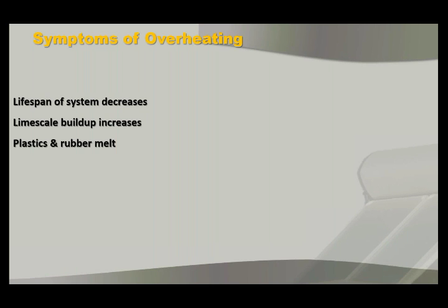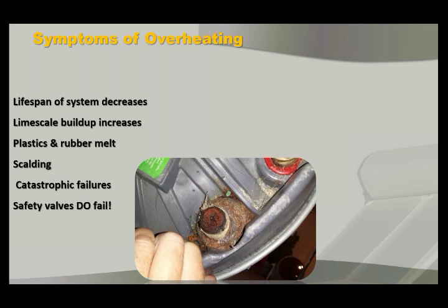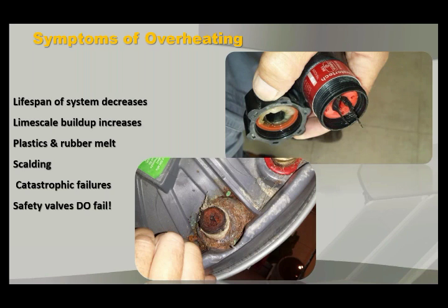And what happens when a system overheats? Now, these pictures you're going to see here, unlike last week when I showed a picture of a cylinder which was installed, these are from my archives, which I didn't have to dig out from 6 years ago. These are all recent happenings in my capacity, and we'll get to that just now. But what happens when the thing overheats? The whole system's lifespan decreases. You're placing stress and strain not only on the tank and the collector, but on all the valves, fittings, and so on and so forth.